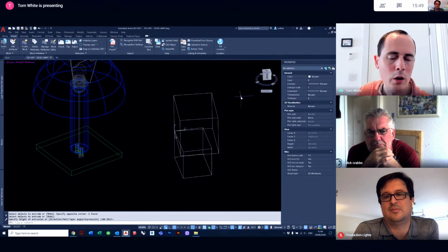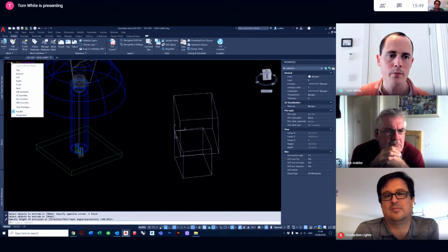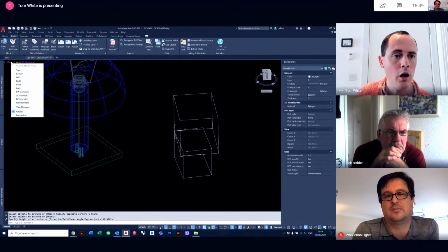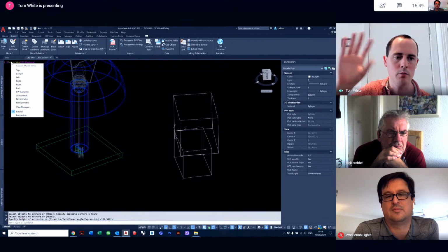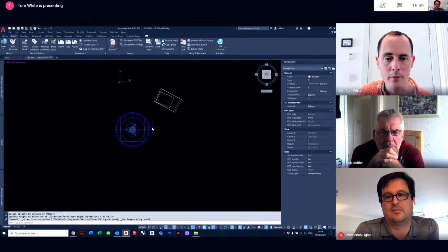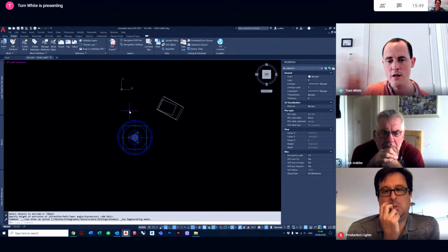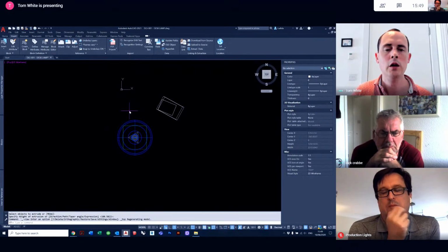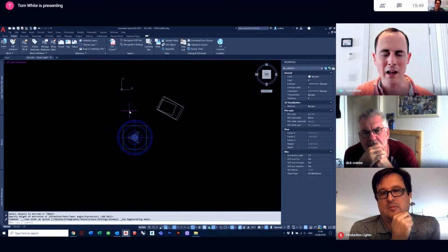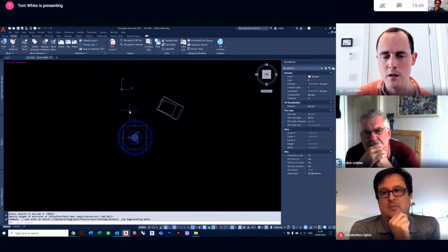In my opinion, one of the quickest ways of rectifying it is to go to the top left-hand corner of the drawing, to what is deemed by AutoCAD as a custom view, i.e. anything other than top, bottom, front, back. I'm going to click on top. What this has done is take me from an isometric or side view to a plan view, our original plan view. And the most important thing is it moved the UCS back to the world coordinate system location.